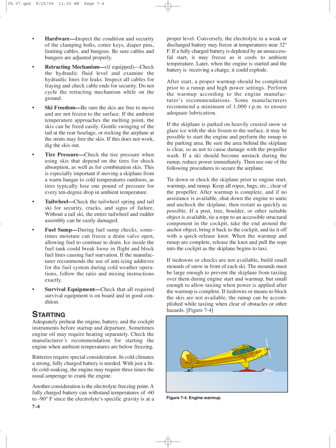Starting: adequately preheat the engine, battery, and the cockpit instruments before startup and departure. Sometimes engine oil may require heating separately. Check the manufacturer's recommendation for starting the engine when ambient temperatures are below freezing. Batteries require special consideration. In cold climates, a strong, fully charged battery is needed. With just a little cold soaking, the engine may require 3 times the usual amperage to crank the engine.